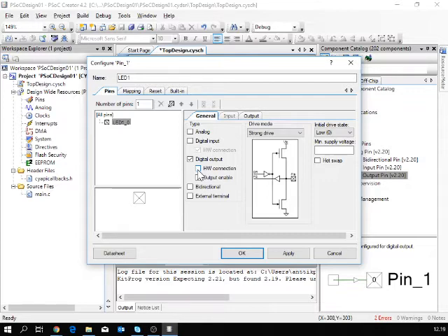Has anyone been writing code with the 8051 variants? 8051 variants usually have an open collector output. So mostly no problems on the driving, but it always requires some external components. Let's take a look at the drive mode.